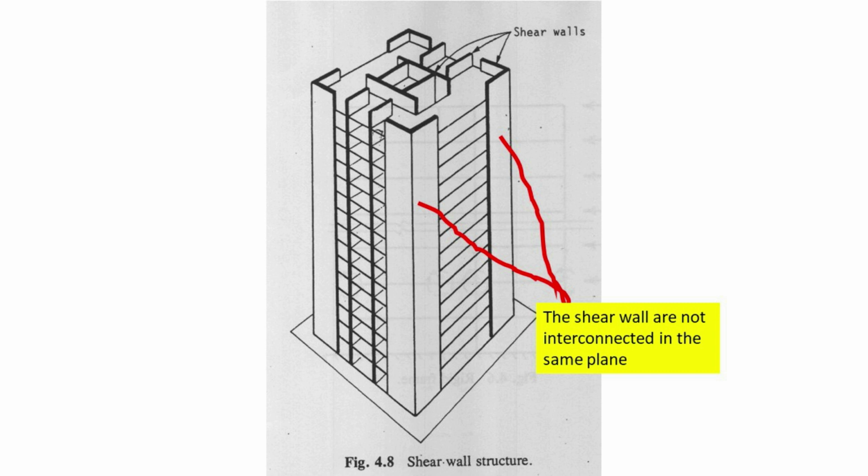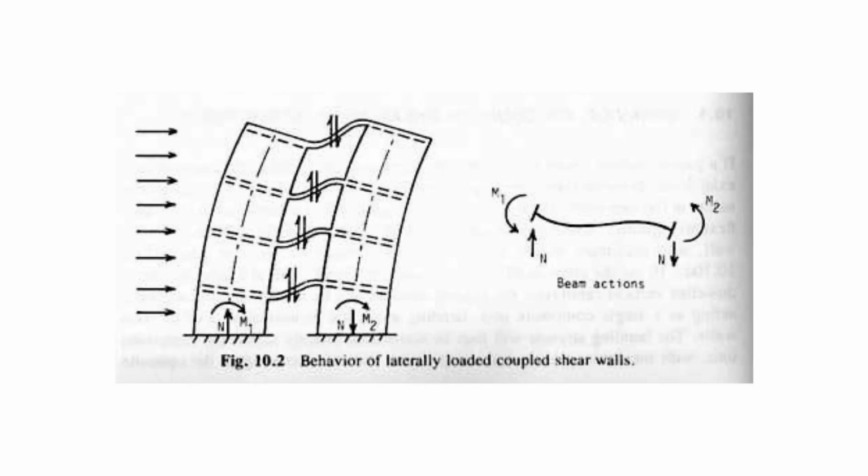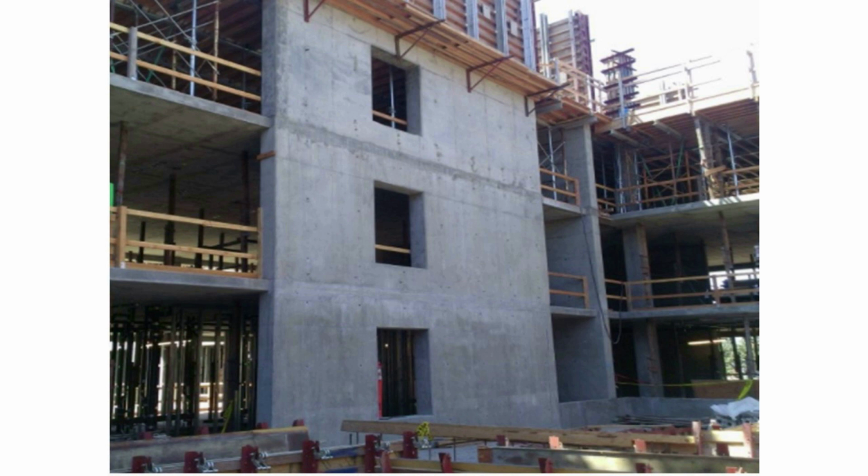Shear walls are more appropriate in reinforced concrete structure. When the walls deflect under the action of the lateral loads, the connecting beam ends are forced to rotate and displace vertically. Therefore, you can see that the beams bend in a double curvature and thus resist the free bending of the walls. The shear also induces axial forces in the two walls, tensile in the windward wall, and compressive in the leeward wall. Here is an example picture of a coupled shear wall.